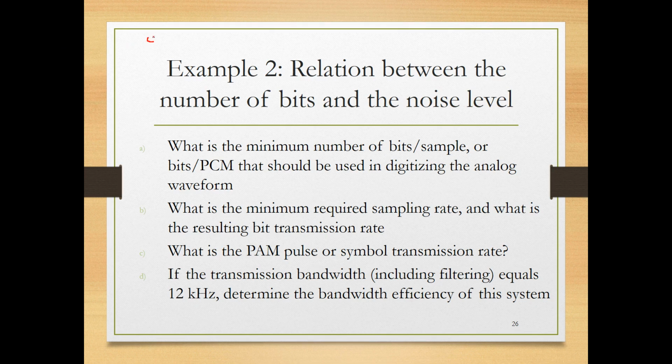Before modulation, you have a sequence of zeros and ones, isn't it? PCM sequence. We converted the samples into bits, and we found the bit transmission rate. Each sample has 6 bits. 6,000 samples multiplied by 6. We found the bit transmission rate is 36 kilobit per second. Now I have a sequence of bits, zeros and ones. I want to modulate it using pulse amplitude modulation. Since I have 16 levels of pulse amplitude modulation, how many bits for each level? 2 to the power how much equals 16? 4, isn't it? Then I take 4 bits by 4 and map them to one amplitude level.